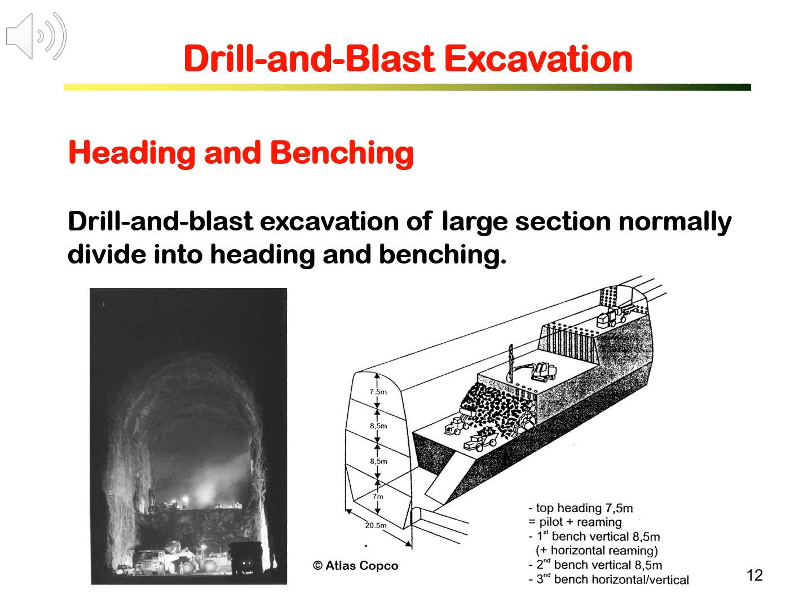Heading is usually done as top heading that allows the roof to be temporarily supported and safe for subsequent benching. The top heading in the right illustration is done as a heading and reaming or side slashing. In terms of excavation cost, heading always costs more than benching.